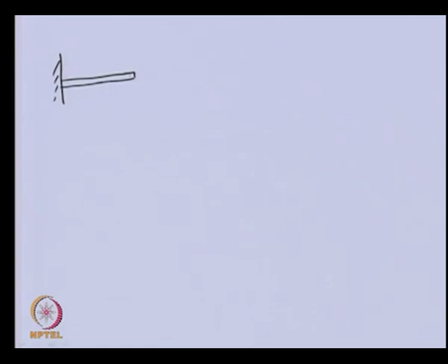It is having torsional stiffness, let us say KT. This is the relatively thin shaft, and this is a flexible shaft whose mass or polar mass moment of inertia we are neglecting. This is a thin disc which is at the free end of this particular rotor system, and we have oscillation of this, let us say phi z about the z axis, this axis is z. So this is the rotational displacement of the disc about its own axis.